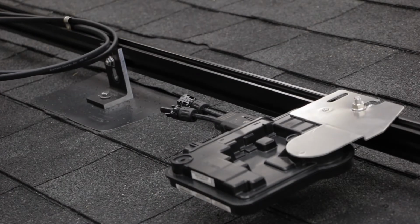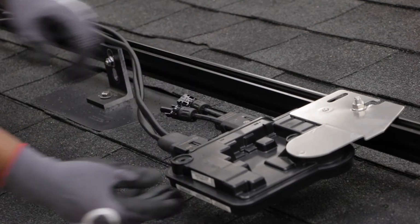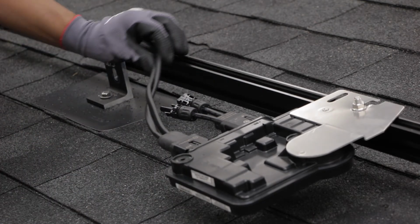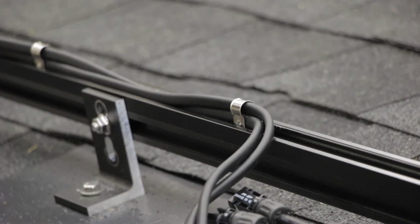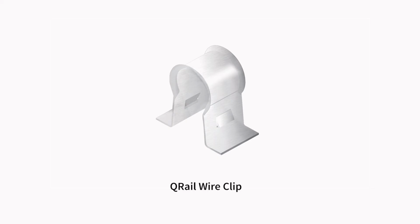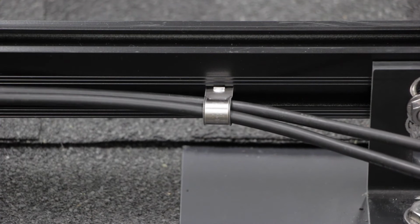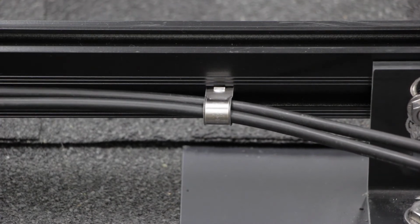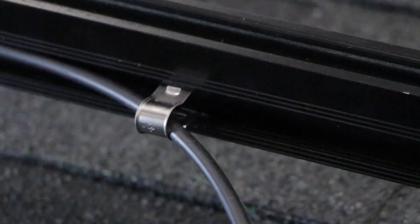Whether you are using module-level electronics or not, you will need to secure wires to the rail. The QRail system allows for wires to be attached to the rail with wire clips that clip into any of the channels on the rail. QRail features a fast-installing stainless steel wire clip that can fit 1 to 3 PV wires. The clips respond to tension, so pulling wires through is quite easy. Squeeze the wire clip and insert one hooked end into the channel and then rock in the other hooked end. The clip will click into place.